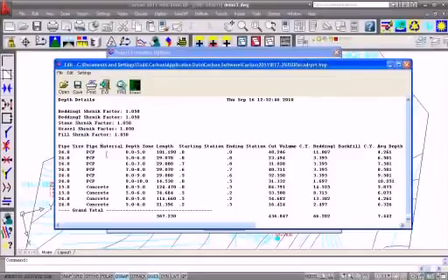Now what we have is a report showing the pipe size, 24, and pipe material, and the depth and the linear footage of those pipe types at those materials. So, 24-inch PCP, there's 100 feet of that between 0 and 5 feet deep. If I had 24-inch of concrete, I would see the length on that as well. So I can see the linear footage of all those things broken out.